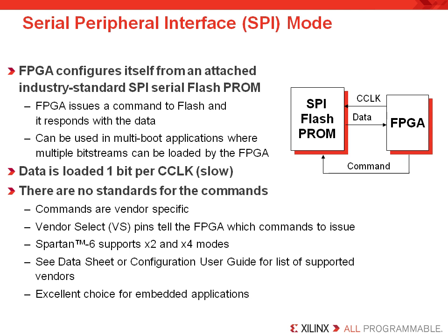If you're building an embedded application, it is also possible to store your software code in the flash PROM as well. So, likewise, plan on choosing a PROM large enough to store your software. Note that the available SPI flash PROMs use a single 3.3 volt supply voltage. All of the FPGA's SPI flash interface signals are within specific I/O banks. Consequently, the supply voltage for the I/O bank must also be 3.3 volts to match the SPI flash PROM. This implies that any I/O pins assigned by the user into the I/O bank must also be 3.3 volt compatible.